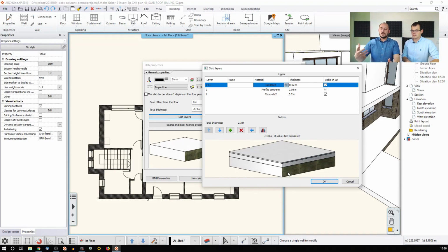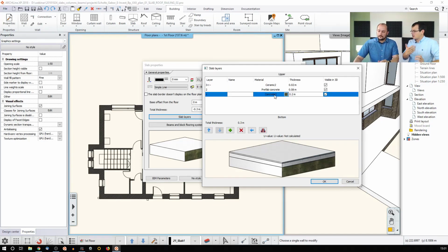And this is the way actually you can define how it will look like when you do the regular architectural section. Materials define how the architectural section hatch looks like. Oh, so you don't have to set up the hatches one by one. You just have to set up the appropriate material, and that would govern how the two-dimensional. Yes.